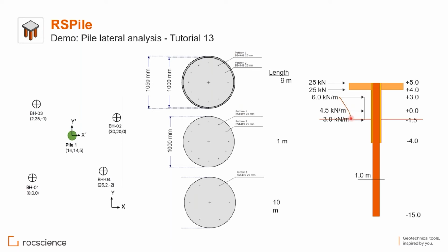And I have a traction force from the wave action laterally applied to the pile. And I have two horizontal forces here, 25, 25. In fact, it's 50, but I divided it into 25, 25. It doesn't matter as long as this part is not rotating. So wherever you put the point, the forces, you will get the same results.